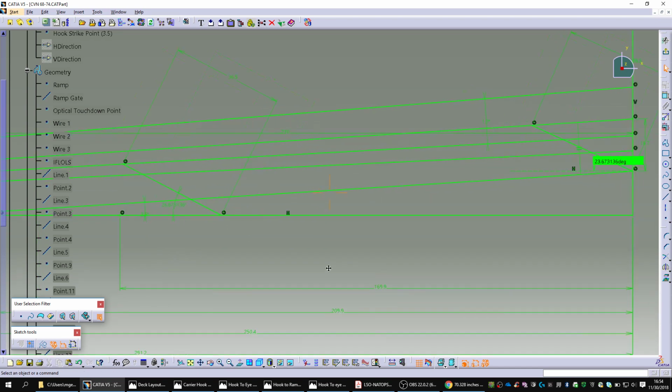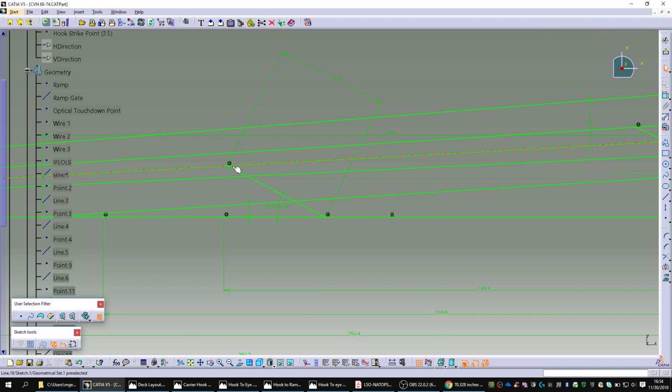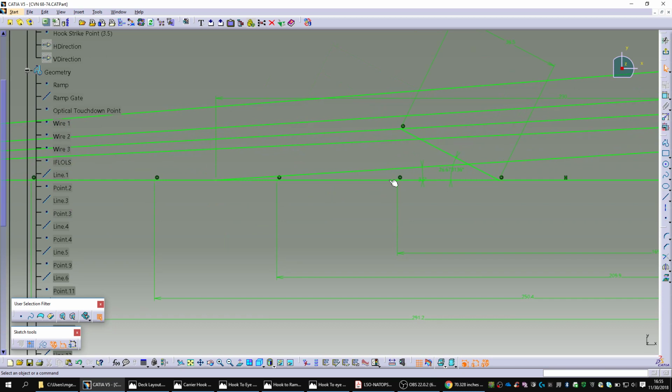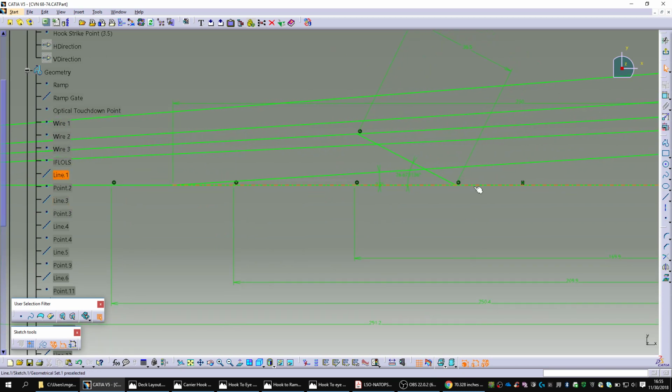But anyway, I've basically duplicated that plane at proper on-speed AOA, down here, having ridden that lower amber meatball all the way down. And where does that strike? It strikes some distance before the one wire. That's kind of scary. 33 feet before. Well, it just turns out that the distance between these wires is about 40. So that's almost like, if there were a wire 0, it'd be right there.